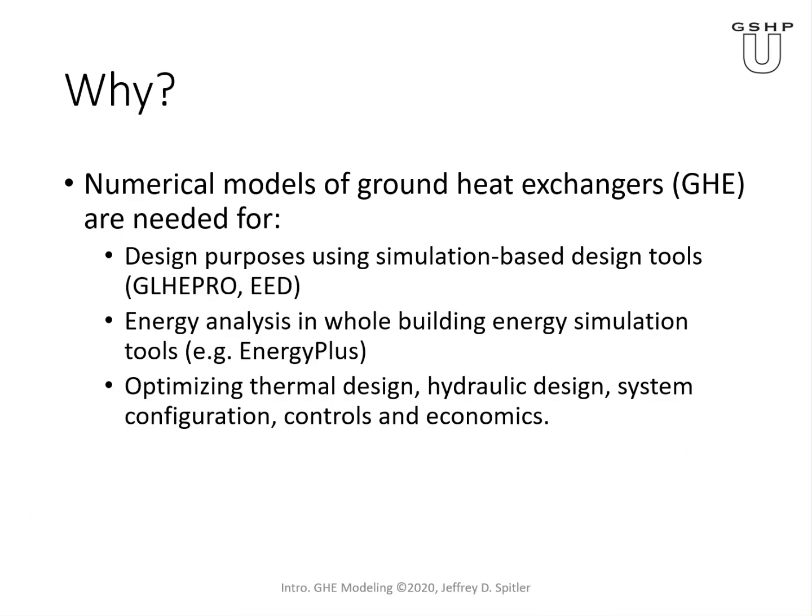So, why do we want to do this? Well, we need numerical models of ground heat exchangers for several purposes. The first one is design. When we're using simulation-based design tools like GLHE-Pro and EED, we're using the simulation and adjusting, for example, the depth or possibly the number of boreholes, the configuration and the depth automatically to meet a user-specified minimum and maximum entering fluid temperatures. So in that case, the engine is the simulation.